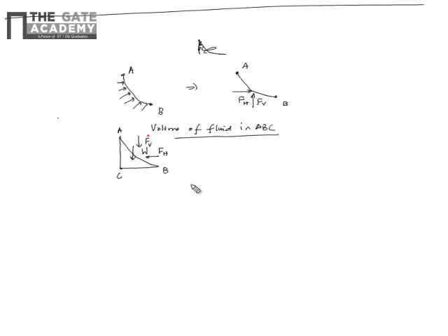So these will be like this. Weight will be W, the weight of the fluid here. Now at BC you have some bottom force because there will be some pressure, and you have some force FAC because of the left side fluid. So if you do a force balance, FH is nothing but FAC, which is the force on that AC.